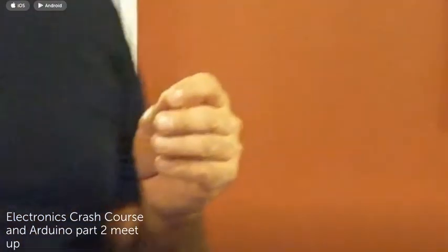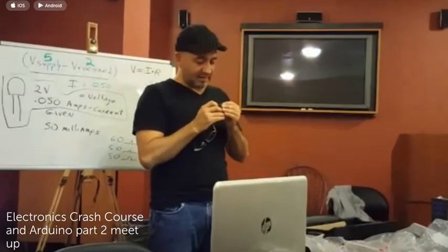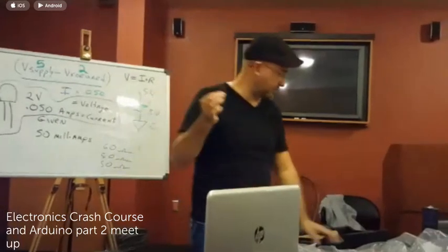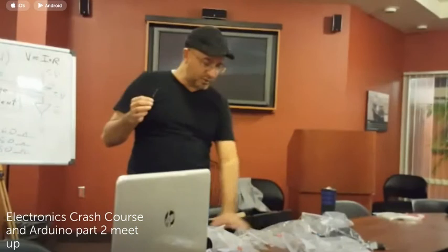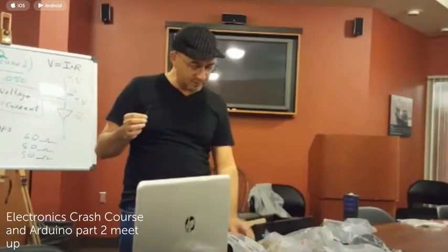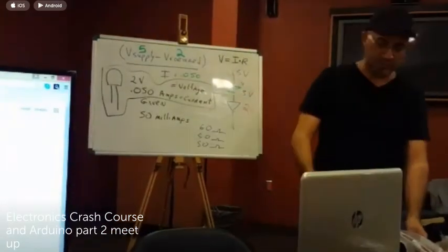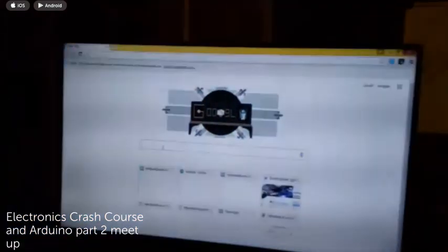The one at the end, the gold, tells you the tolerance, how accurate it is by a percentage. The brown, the black, and the yellow tell you how many ohms there is in the value of this resistor. So look on Google and see if you can find the chart and tell me what 3 colors make up a 60 ohm resistor. Let's start with the 60 ohm.